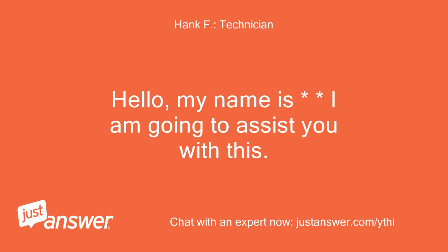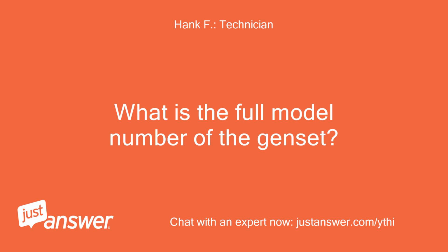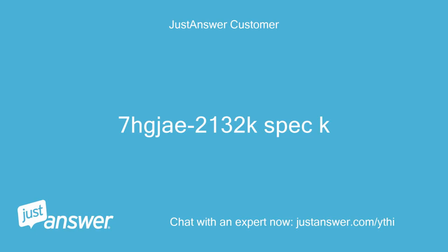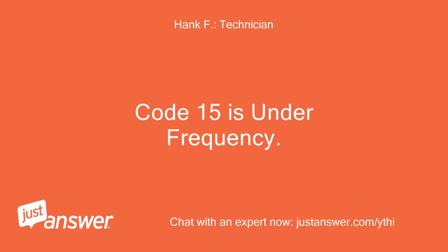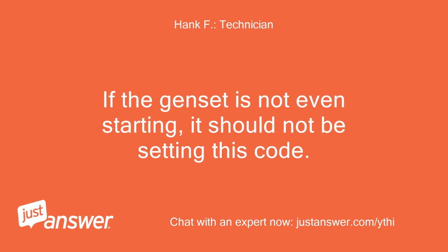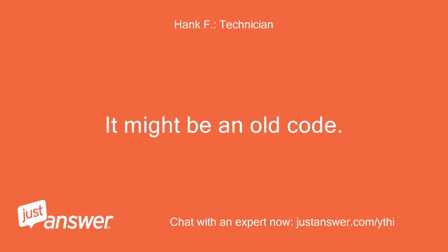Hello, my name is, I'm going to assist you with this. What is the full model number of the genset? 7G2132K spec K. Code 15 is under frequency. If the genset is not even starting, it should not be setting this code. It might be an old code.